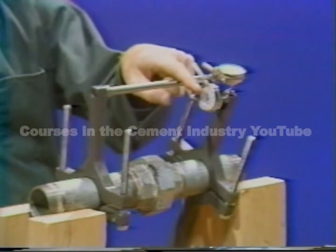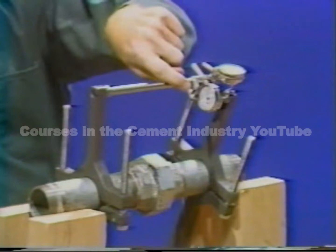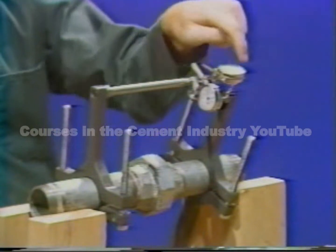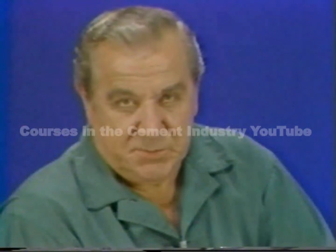On this one, the plunger will pick up changes caused by angular misalignment because it's resting against the face of the post. This one will pick up offsets because it's resting against the top of the post. That's the setup we'll be using during this program.